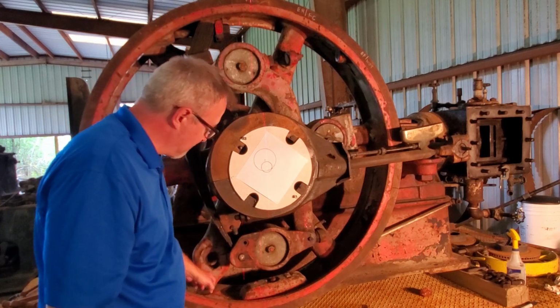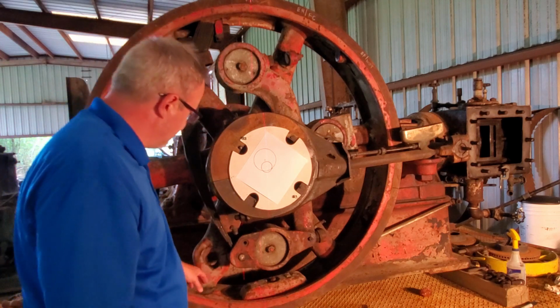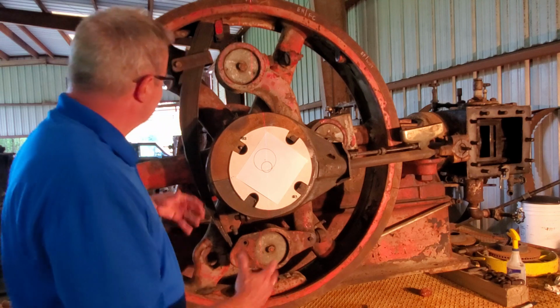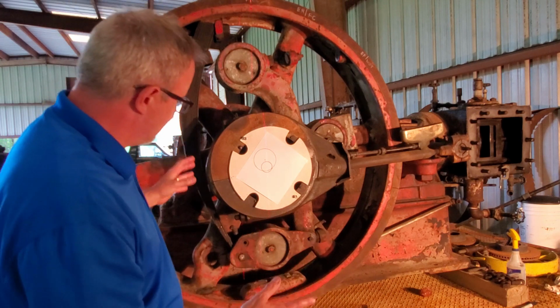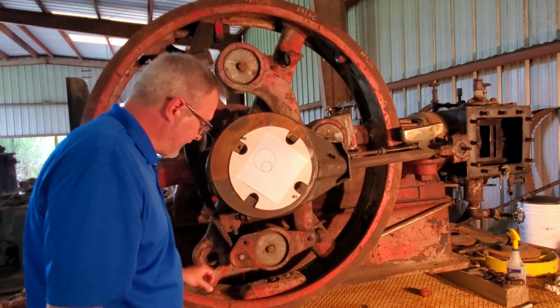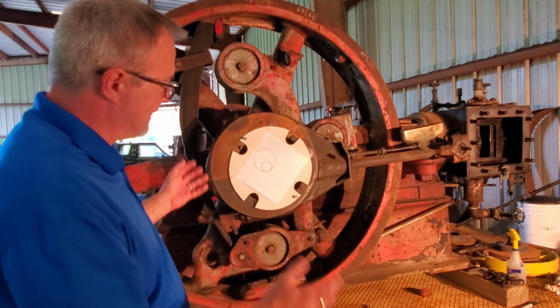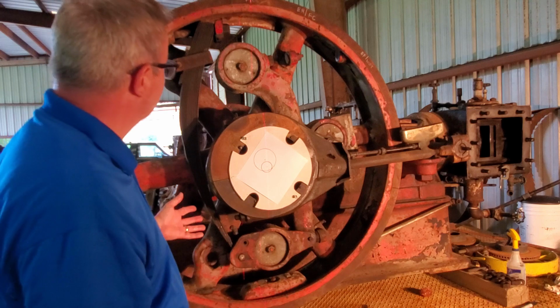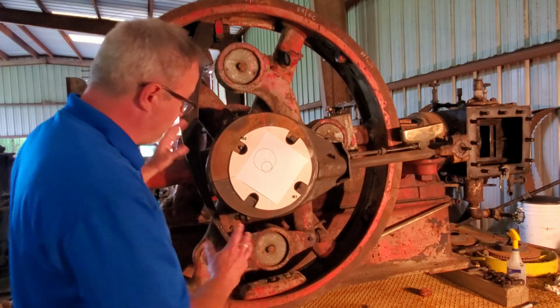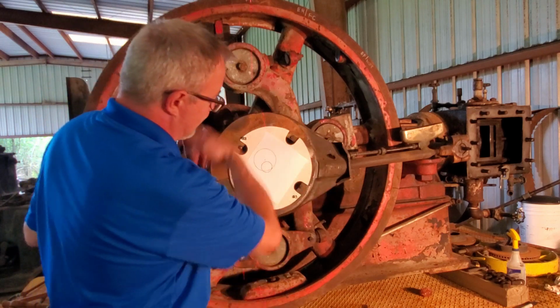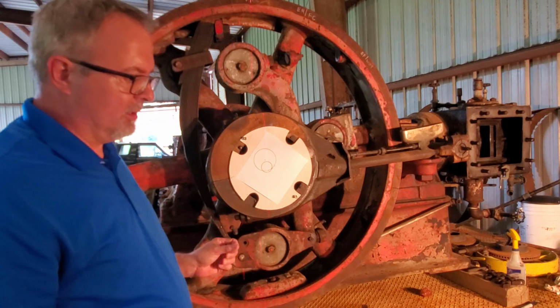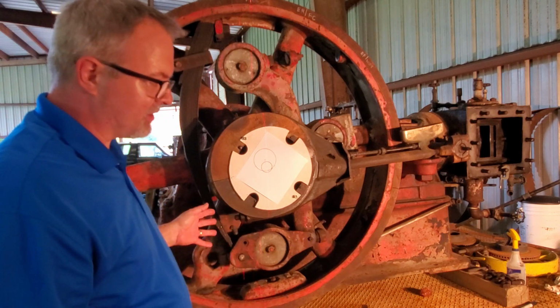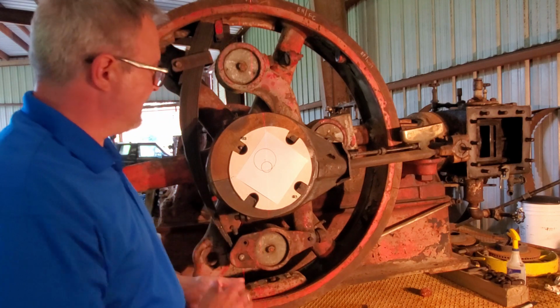You would have to make some modifications to the flywheel. It looks like they've accommodated it, because they do have the casting for it, but it's not universally drilled and tapped and set up so that it can run in either direction. So we're stuck with running in this direction. We'll just make all of our line shafts and counter shafts work with that as it is.